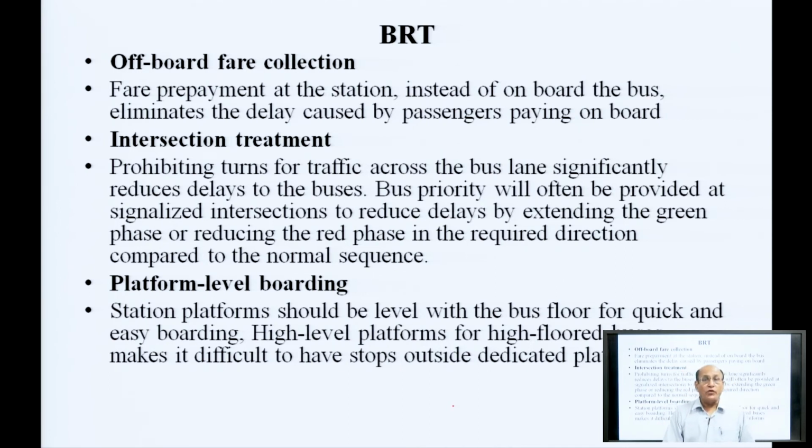Off-board fare collection. Fare prepayment at the station instead of on board the bus eliminates the delay caused by passengers paying on board. Intersection treatment. Prohibiting turns by traffic across the bus lane significantly reduces delay to the bus.